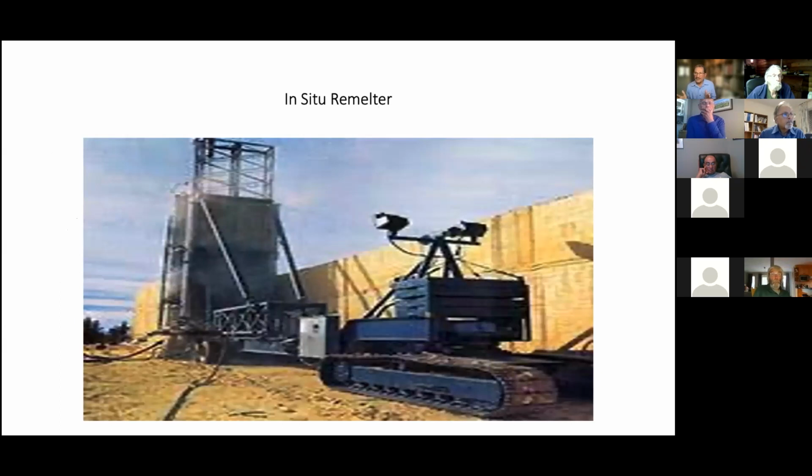So basically what it is, you see this big rectangular thing, whatever it is. It has heating coils at the end, vertical serpentine heating coils. What it does is it presses against the block and melts the sulfur. The sulfur runs down into a collection trough at the bottom, and then it's drained down into your collection tank, pit, whatever. This is what was used initially in the 80s and all that.